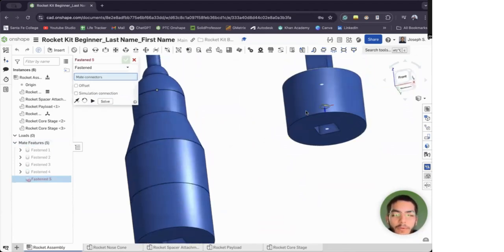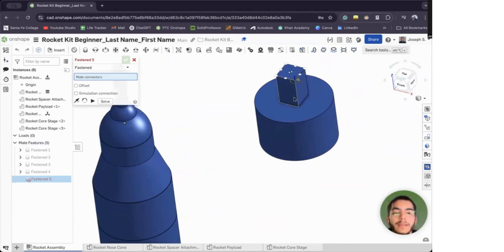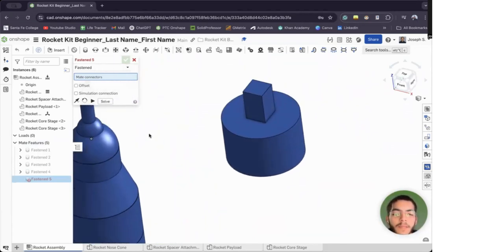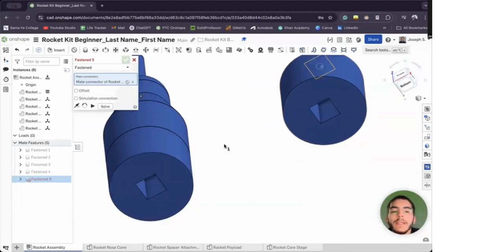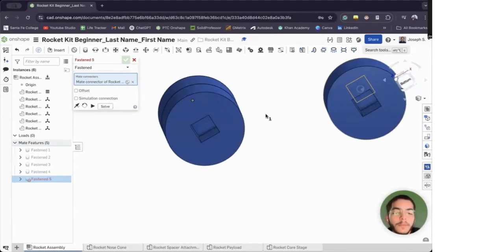The reason behind what I'm doing, and the reason behind the connector looking like this, is that when it's 3D printed, if you have a physical rocket kit, you've experienced assembling it together and seeing how it connects. This is just the CAD version of it, the model designing process of figuring out how to design it in the computer so that when you print it out or manufacture it, it attaches together, right? And these measurements that I put, 0.41, 0.71, I had to prototype to see which measurement works best for attaching the pieces together. So it just worked best in my case, the measurements I put.